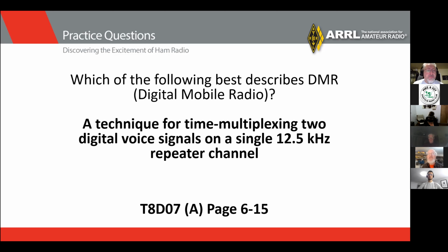You're going to have an A channel and a B channel. This Anytone is a DMR radio. You get into what they call talk groups, and those people in the talk group can hear you. A talk group can be pulled up on maybe 20 different repeaters at one time. We've got Washington 1, Washington 2, and Seattle ACS has a couple of talk groups. There are hundreds of talk groups out here.